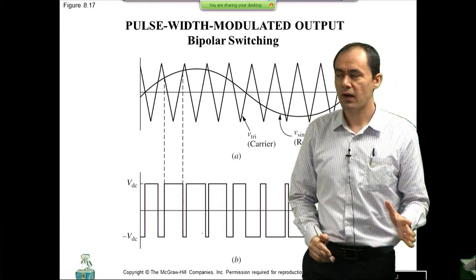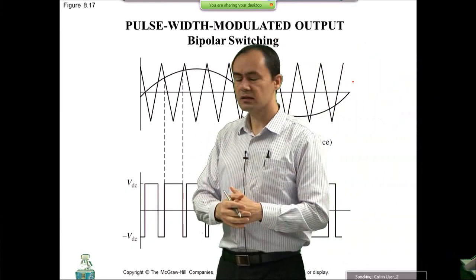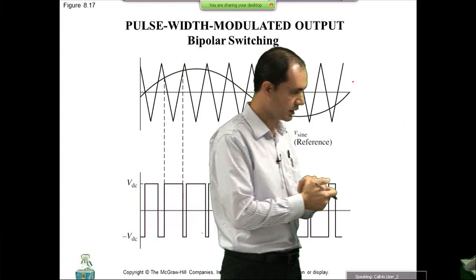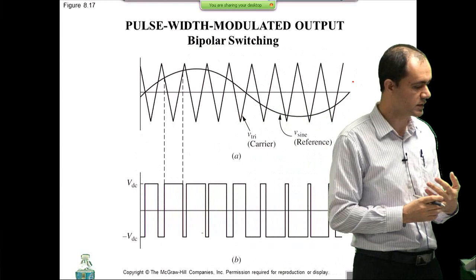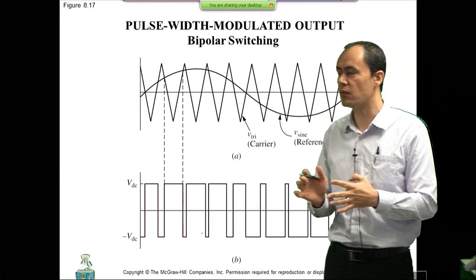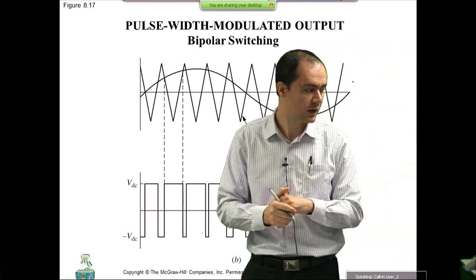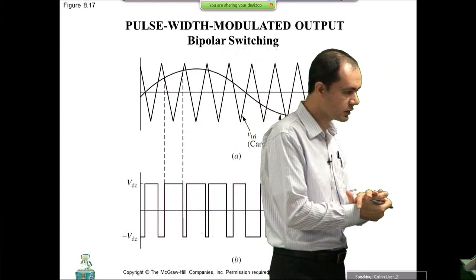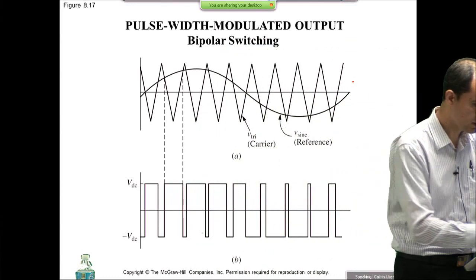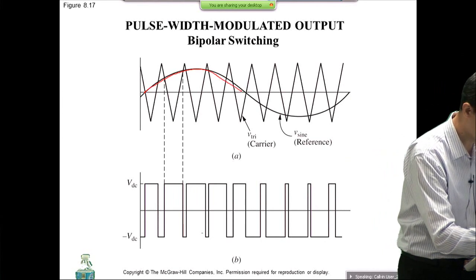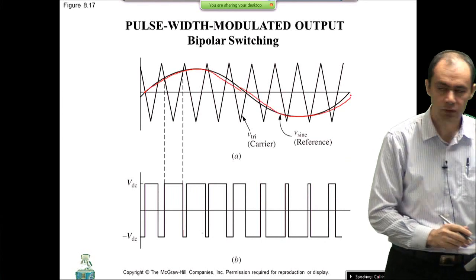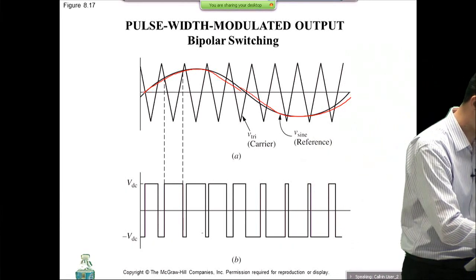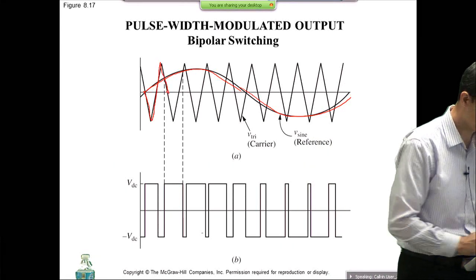Okay, now then, still on the single-phase topologies, we introduced the PWM switching scheme. And the difference over here is now we are making decisions on what switch should be turned on or off based on the comparison that we make between a sinusoidal signal, which is kind of our reference, which is this guy over here, and a relatively higher frequency triangular waveform, which is called a carrier signal, which is this guy.